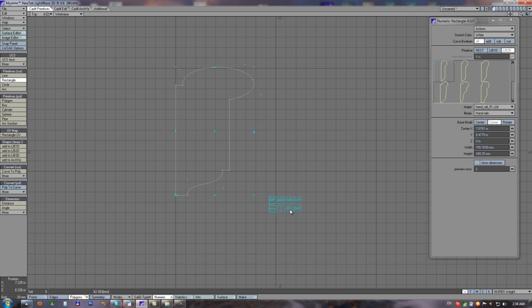With the fix button we can freeze the dimensions of the tool, and now we are just moving the frozen object. After the unfix button, we can again adjust the dimensions, and with the default button we will revert the dimensions of the object to the factory settings of the shape stored in the library.